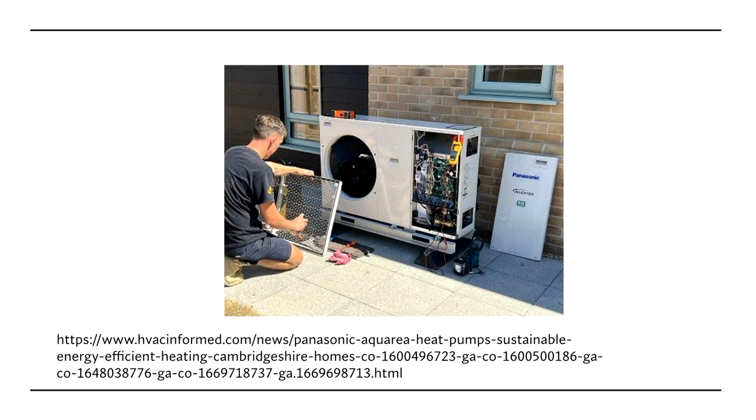We don't use pressure washers because that damages the fins on the coil. But we want to get in there with some special coil cleaner, and it'll dissolve all the grease and dirt and anything else that's in the way and blow it out. Okay.